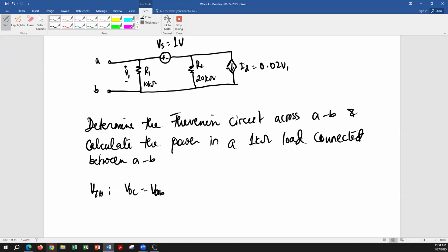On top of R1? Okay, and if you do that, then you have two currents, one going through R1, one going through VS, but how are you going to write down that current that's going through VS? I mean, you can use a super node if you want. It's just going to make it a little more complicated. Yeah, there's a node on top of R2.